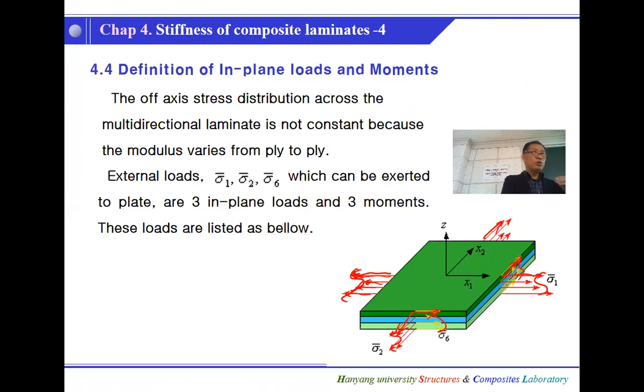Of course, if you have a thicker ply or a thicker laminate, we need to consider this guy, the out-of-plane shear stress. Those stresses can play a very important role, as big as this in-plane stress. But again, we are focusing on thin ply laminates. So that's why we only consider in-plane stresses. Okay, so this is the observation of stresses.